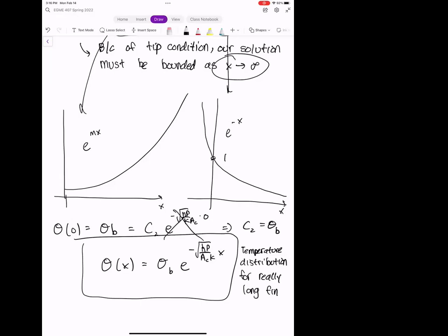Except condition 4 is a little bit more strict, because condition 2 we can achieve the same conditions without having a really long fin, as long as your tip is very, very tight. So four is a little bit more restrictive because we're requiring the fin to be really, really long, but it also accomplishes the same thing as condition 2. Good observation.